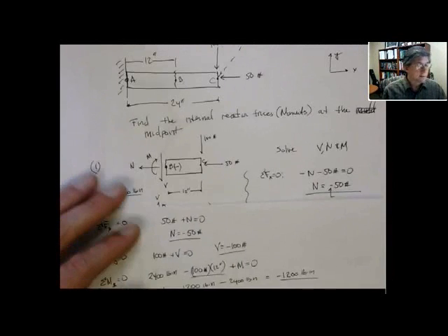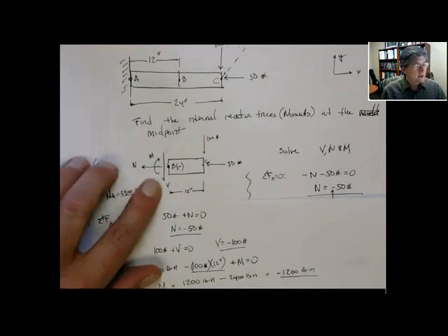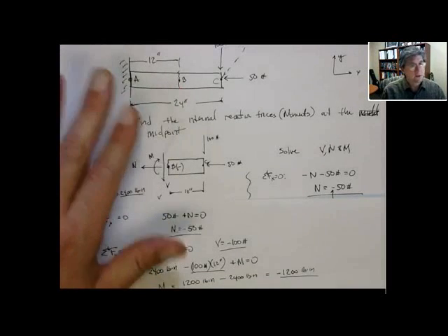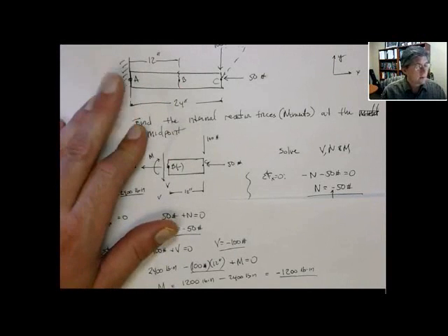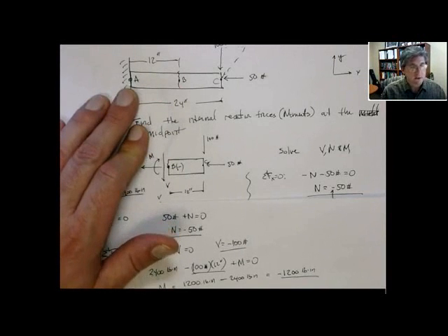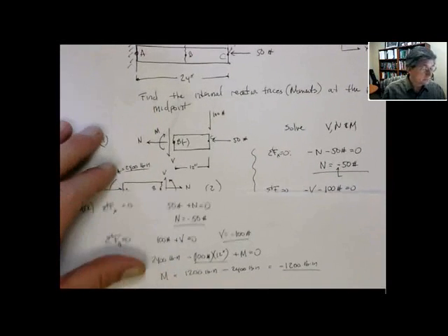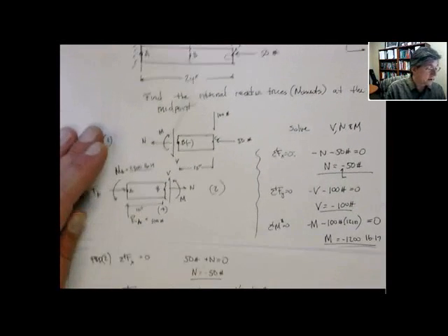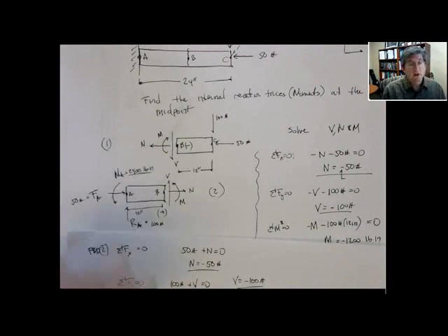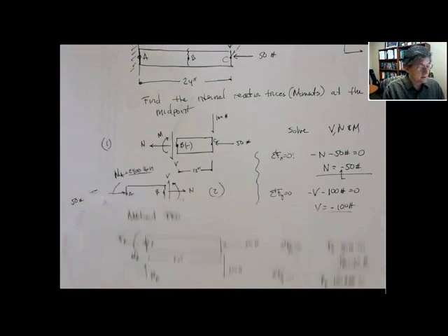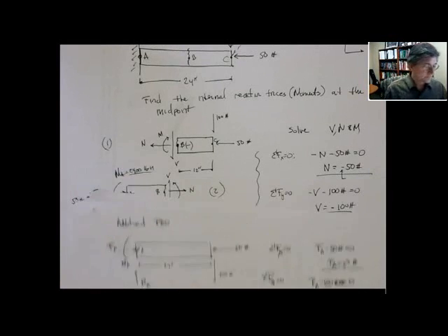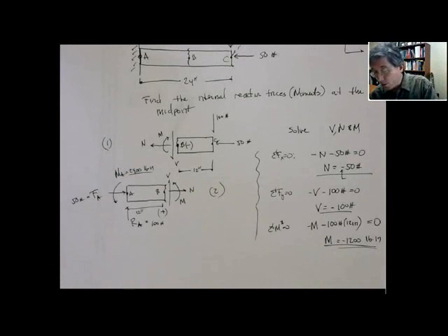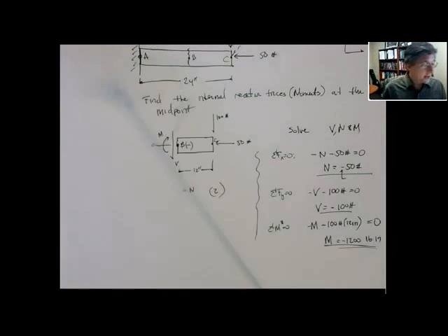As you get good at these and practice, you know, your homework, you'll find it easier to choose which ones work better. Usually, it's a good idea to try and pick a free body diagram that uses fewer reaction forces from constraints. Now, you might not always be able to do that, and if that's the situation, you might have to use an additional free body diagram to determine the external reaction forces. So if you want to go through the steps of doing this,